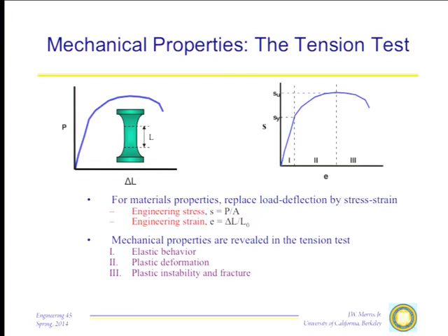Down here where the strain and stress are very low, you get elastic behavior. And in a typical metal, the curve will be linear over that region. You will then begin to deform the material, a permanent change in shape. That's plastic deformation. The curve will bend over and will increase in strength as you continue to deform it. That's a phenomenon known as work hardening. However, as you continue to deform the material, the stress will eventually peak out. That's what's called the ultimate tensile stress.